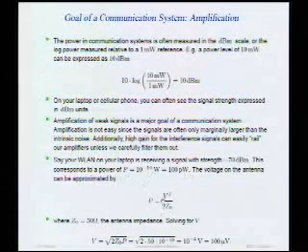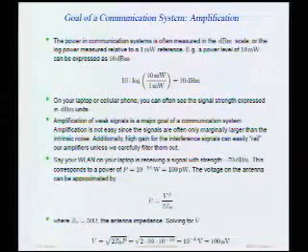And we can translate that into an effective voltage that you see at the input of the LNA, assuming that the input impedance of the LNA is matched to your antenna with an impedance of Z0. If you just translate that into a voltage, basically we know that the power is proportional to voltage squared. That corresponds to 100 microvolts, approximately. Now, that's a small signal, but it's not too bad. We can probably live with that. 0.1 millivolts.